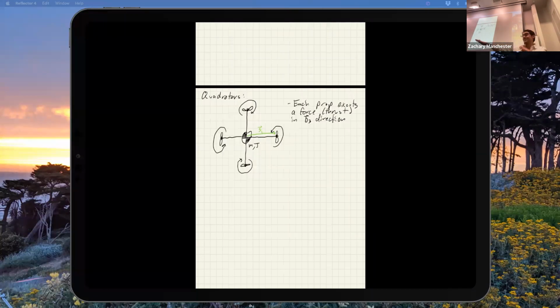This is also why they twist, by the way. You notice propellers are never straight. They always have this twist to them. It's because the wind velocity over the propeller changes as you go out from the root to the tip, right? At the tip it's moving faster, and inboard it's moving slower. So you want to vary the angle of attack as you go out, because the airflow is different speeds. Anyway, that's a whole other thing. So you get torque in the plus or minus B3 direction.